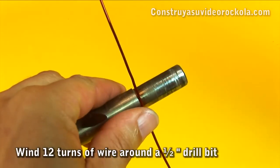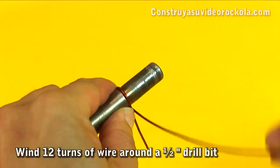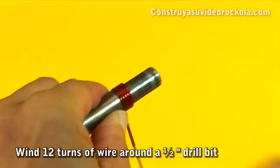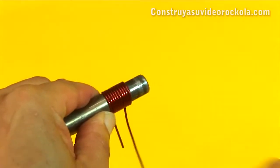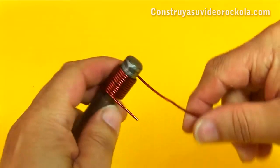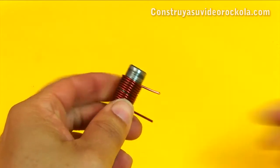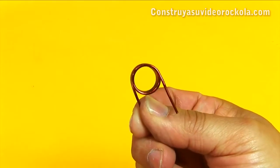Assembly. We will begin by making the coils. We take enameled copper wire, and around a 1/2 inch drill bit, we roll up 12 turns. They must be well aligned, and without spaces between one turn and another turn. We cut the excess wire. The coil should be as perfect as possible.